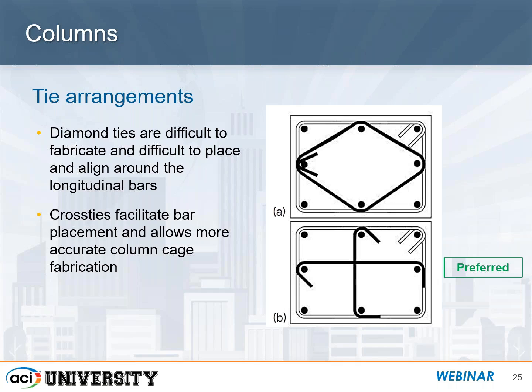Having this informal poll through the years has led me to conclude that diamond ties are a little more difficult to fabricate and to place than your standard cross tie like this. And it makes sense. Once again, if things are not aligned properly in the field, having to adjust this and get this diamond tie in is more difficult than just putting in these cross ties.